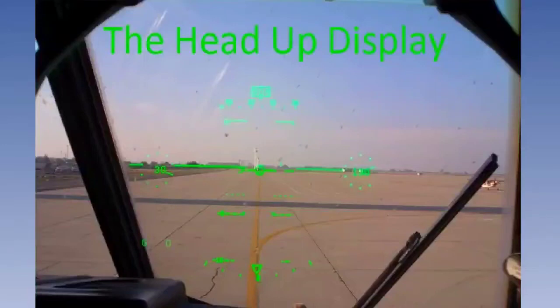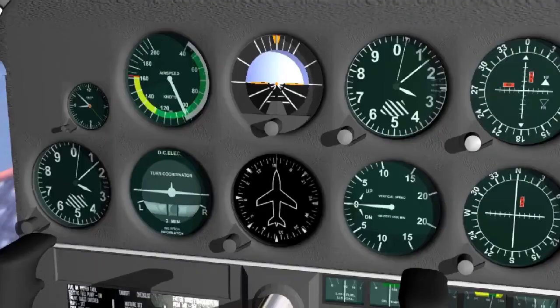A head-up display, or HUD, is a method of presenting flight information and guidance so that it appears in the sight line of a pilot looking out of the windscreen. Its primary advantage is that a pilot does not have to transfer his gaze between the view ahead and the traditional head-down instruments, especially at a critical phase of flight.